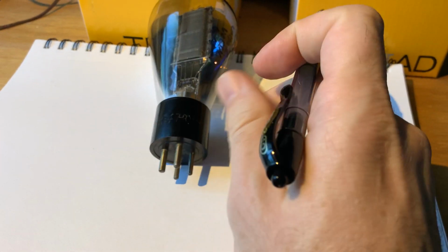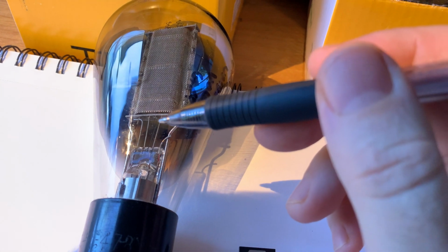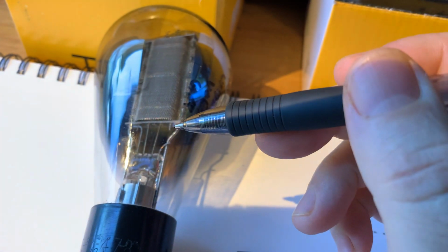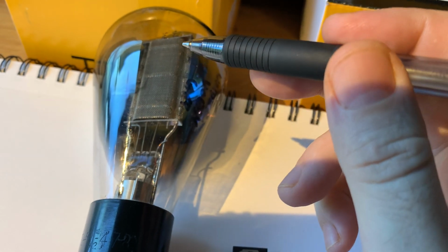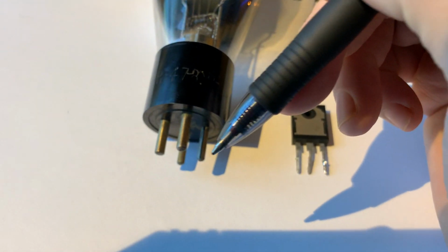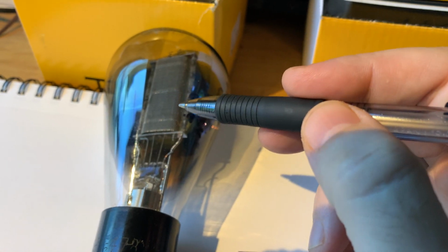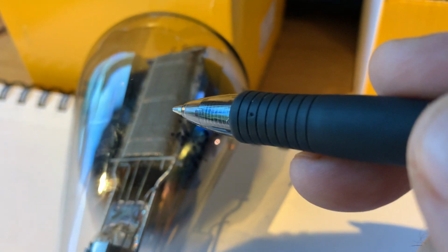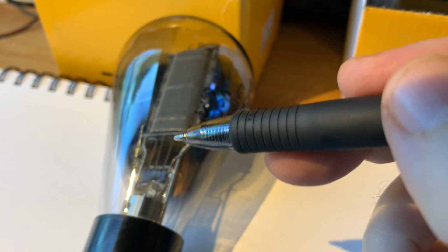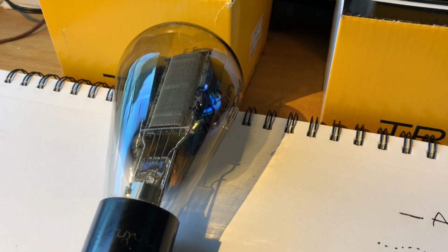And here on the vacuum tube, if you look in the middle, those two wires in the center, that's the cathode. And that tiny piece, that's the support rod for the control element, and that's on the other side, that's the support rod, and that gets connected into one of those small tube pins. So that's the control element, and the big one that you can see, that's the anode, and it's also called a plate in a vacuum tube. The cathode is called a cathode. In the case of a direct heated triode, which this is, it's also the filament, but we'll get into what a filament is, because that's something different.